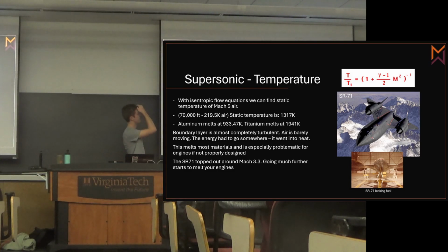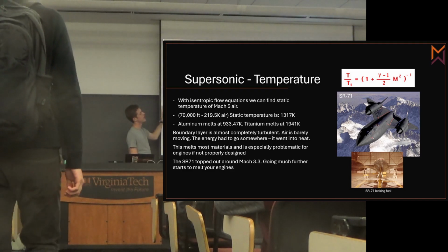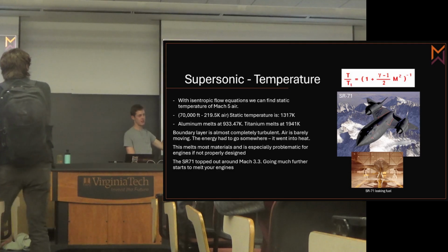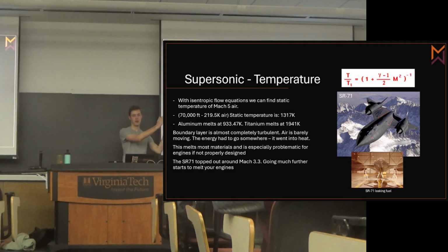Okay. So, inlet temperature. We've kind of neglected the equations here, but there's one at the top, so don't worry. This is saying T is the temperature of the flow, and TT is the total temperature. Which means if I take a volume of air and do all the work to slow it all the way down to no more velocity, it is going to trade all that speed, and it's got to put it somewhere. So it's going to go into pressure, and it's going to go into heat, temperature. So I'm going to heat this thing up.